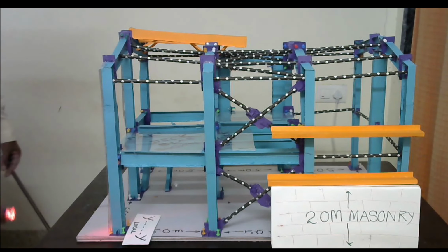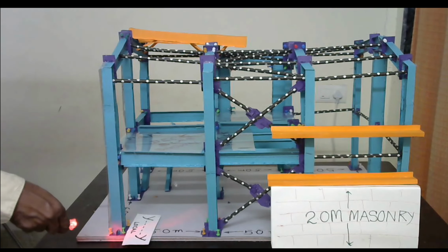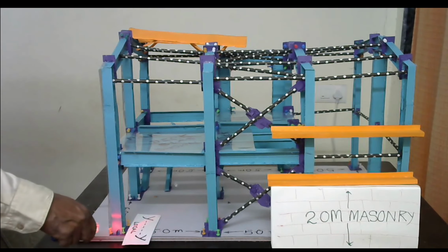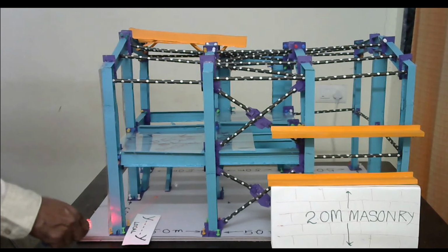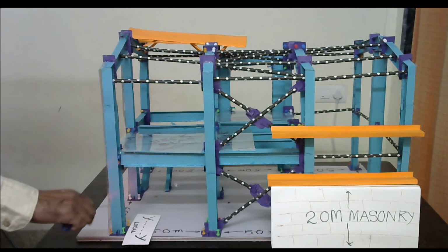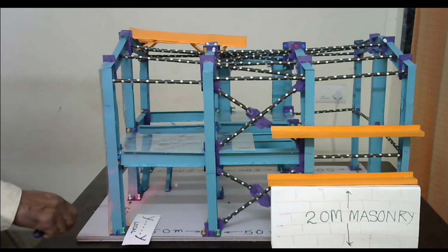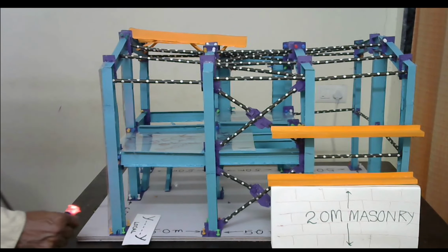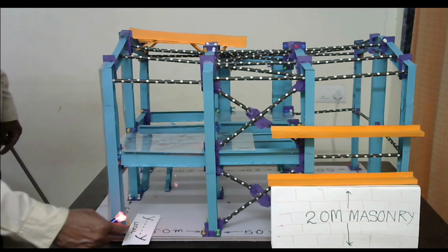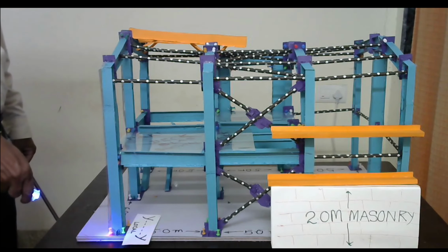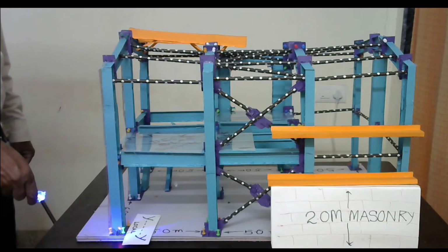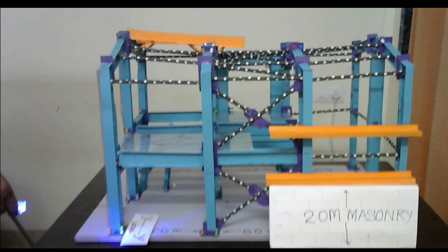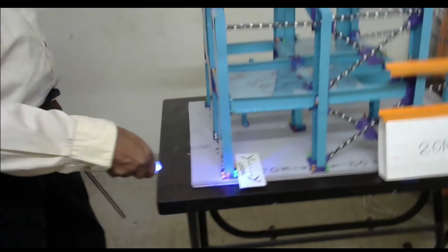You can see there are bolts here, but these bolts are arranged in such a way that this joint behaves as a pin joint about the YY axis. Why? See, there is no flange here. So when these bolts transfer restraint, it cannot produce that kind of restraint which can be considered as a moment connection.